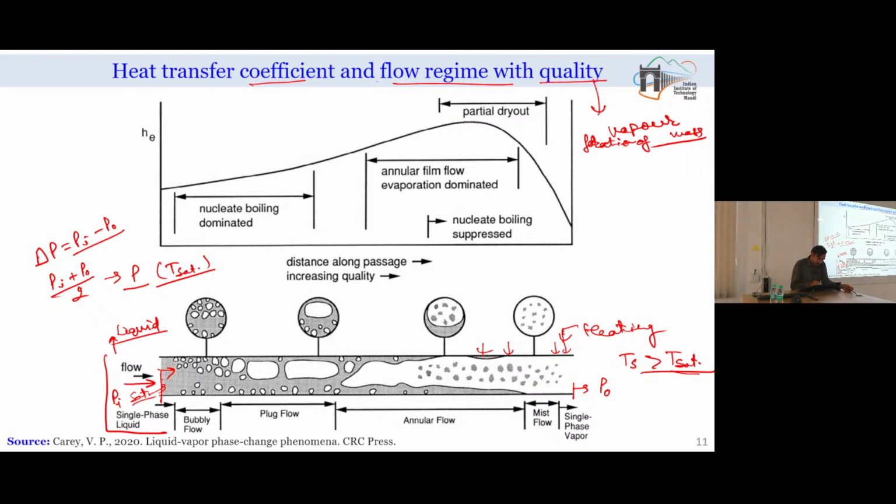Now, whenever we have the refrigerant, or any working fluid, flowing inside this tube, because of the external heating we will find that there will be nucleation at the wall of the surface. All these small bubbles will disengage because of the flow of the liquid, and these will be moving in the forward direction with the liquid. As we move along the tube, we will find that a large number of bubbles are coming from different portions. All these bubbles will have chances to join each other and form bigger vapor volumes. And because the tube is located in the horizontal direction, gravity is acting like this. So, because of this, we will find that the vapor volume, being lighter in density, will stay mostly in the top portion of the tube.